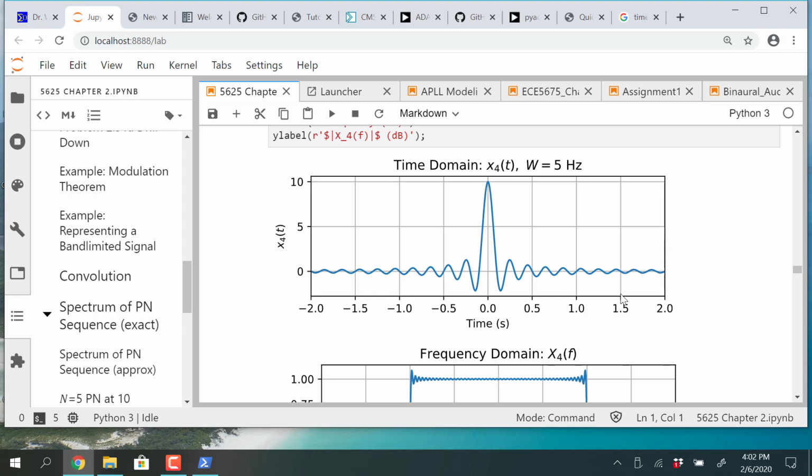The second one is Fourier transform of an impulse train gives you an impulse train in frequency. We'll be talking about that one shortly. Then the third one is the Gaussian. Fourier transform of Gaussian is Gaussian function. Not the exact same shape. I mean, there's a Gaussian bell, but the width of the bell is inversely related from time to frequency, but still true.